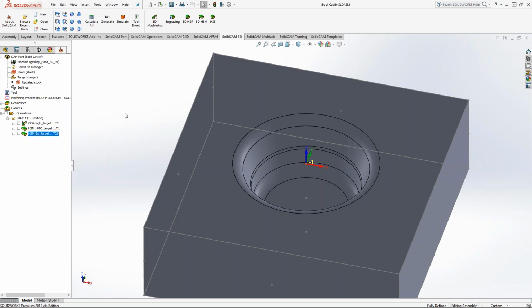So I think that coating is good for stainlesses, Inconel, stuff like that. I think they use that coating for those tools, if I'm not mistaken. But for just the standard hardened materials, I prefer the AlTiN coating. Perfect.